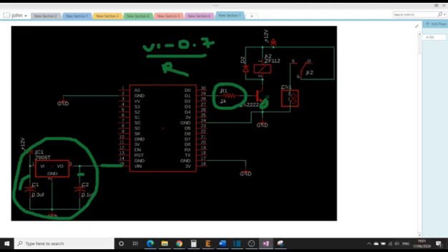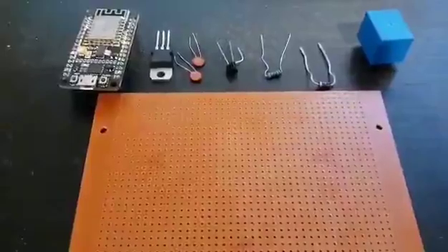And then on the transistor, on the collector, we have connected a flyback diode, which is connected across the relay in order to protect against the reverse current. And also on the relay, we have connected two separate pins, and we are going to use the plus voltage of the LED cable lights and the minus here. And these are the components for the hardware.